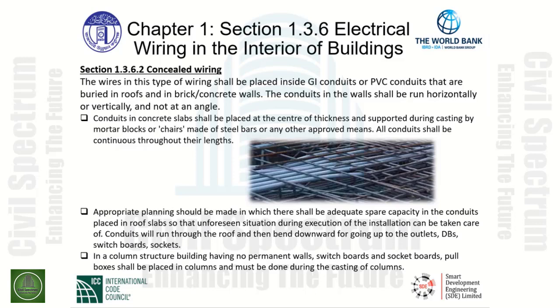Appropriate planning must be made in which there shall be adequate spare capacity in the conduits placed in roof slabs so that unforeseen situations during execution of the installation can be taken care of. Conduits will run through the roof and then bend downward for going to the outlets, DBs, switchboards, and sockets.